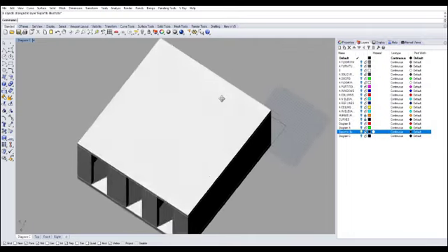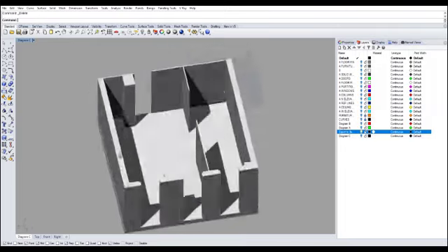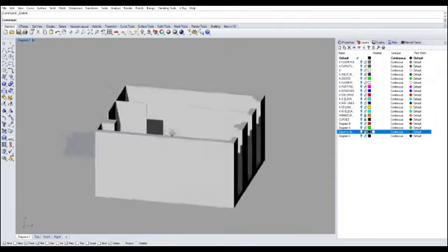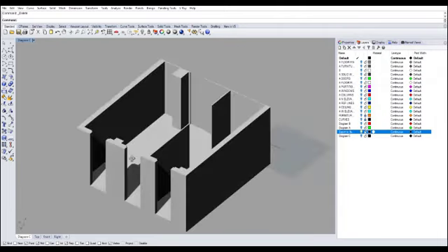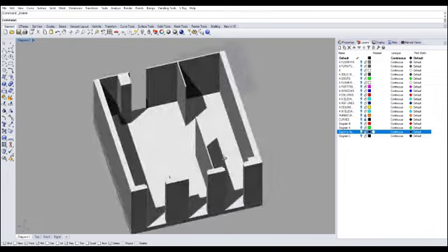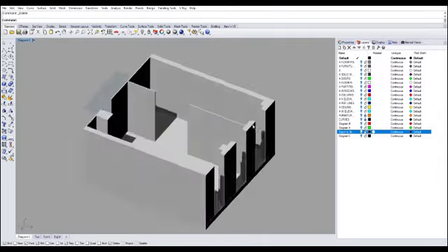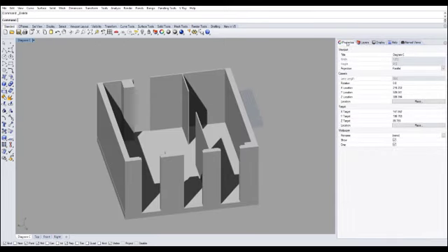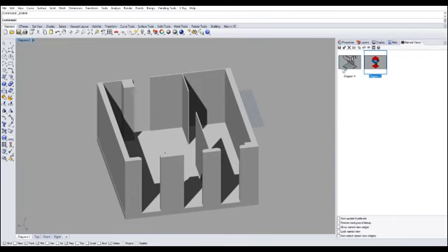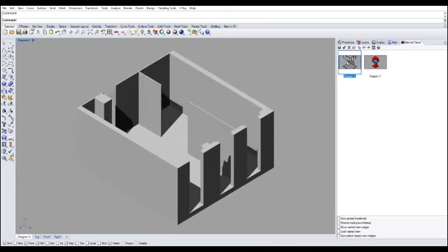So for the one that we want for export to Illustrator, we don't want the roof, so let's just delete that. Now this is ready to go into Illustrator. Now we're not going to bring in 3D object to Illustrator. We want the line work from 3D object to Illustrator. And as I said before many times, consistency and systematic view that we export and preserve for diagramming and drawing exercises. So which means that we also want this view without the roof also be on our previous name view, which is our diagram A view. Not the C. Again, C includes everything, right? No, we want the diagram A view. This is now ready to be transferred into line drawings that Illustrator can open.